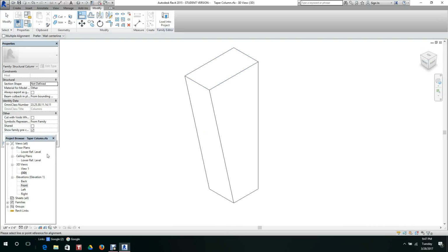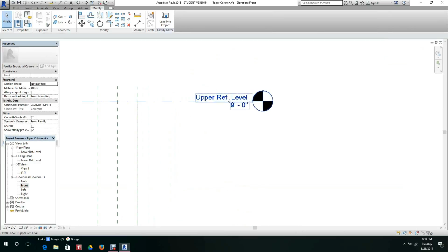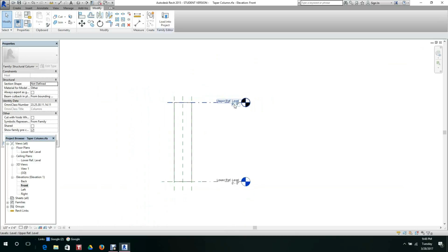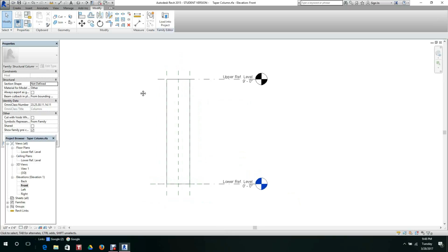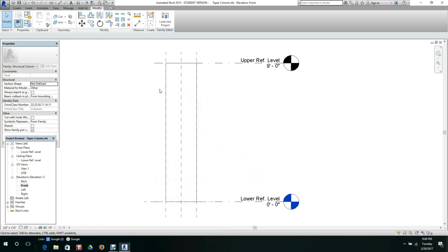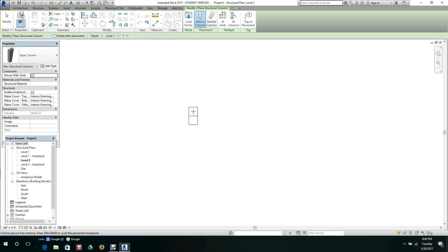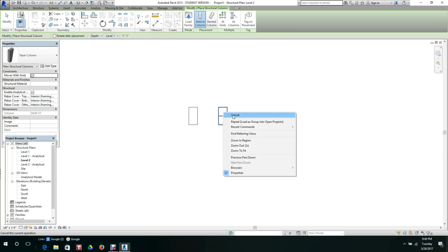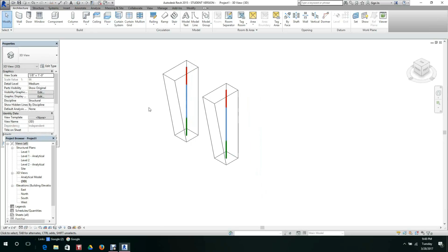And now what happens here, I want to show you guys this in the front view. This taper will adjust to whatever height we change this to, which is going to work out just fine. So what we'll do now is we'll load this guy into the project. And there's our project and there's our column. So we'll place our column, say one there, and look at this in 3D view within our project. Ah, there, looks good. We want to change this to shaded view.